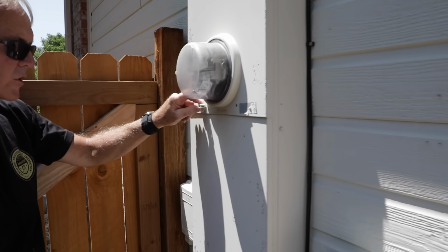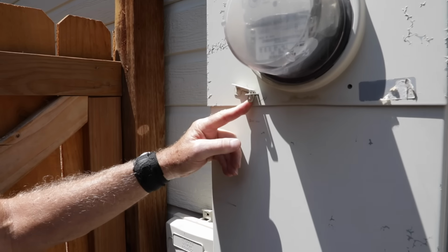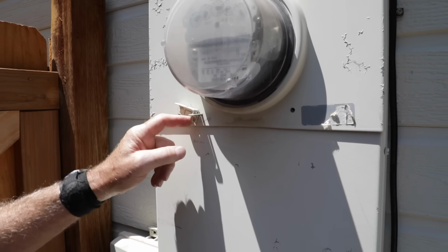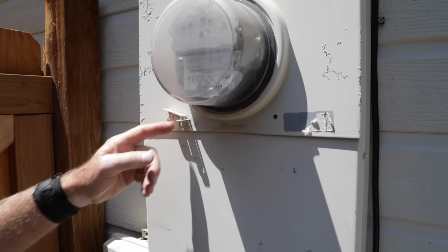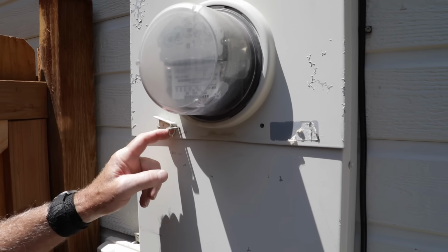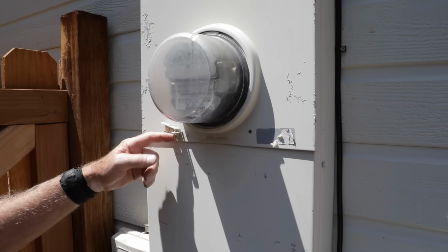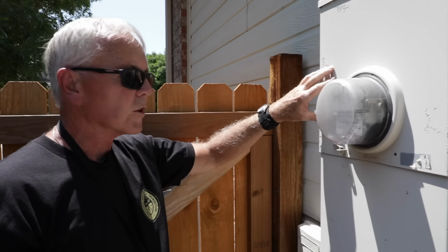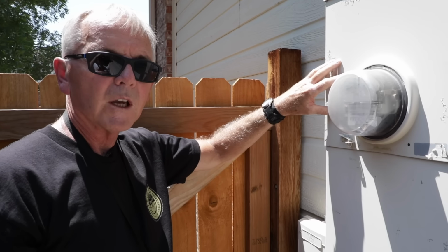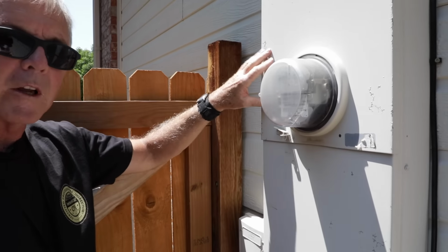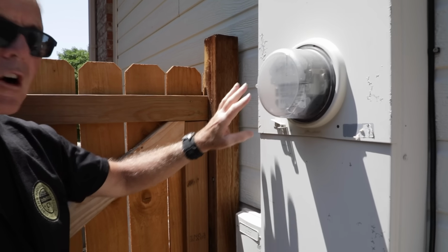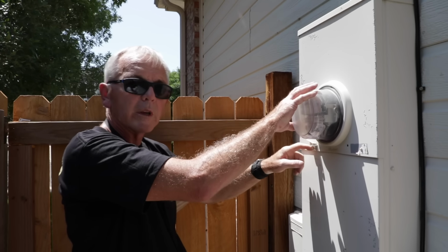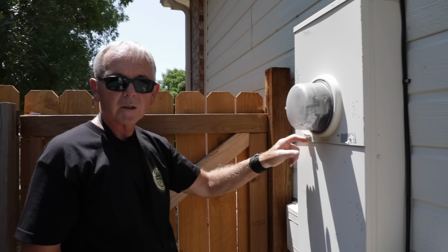The one thing I've noticed here is that there is no meter seal on here. There should be a meter seal that is applied by the utility. This is for security purposes. That way, if it gets cut off, like in this case, it makes you have to be concerned that somebody got in here and made modifications. So I'm going to recommend to my client that they call the electrical utility company to come out and check this meter base and reseal it.